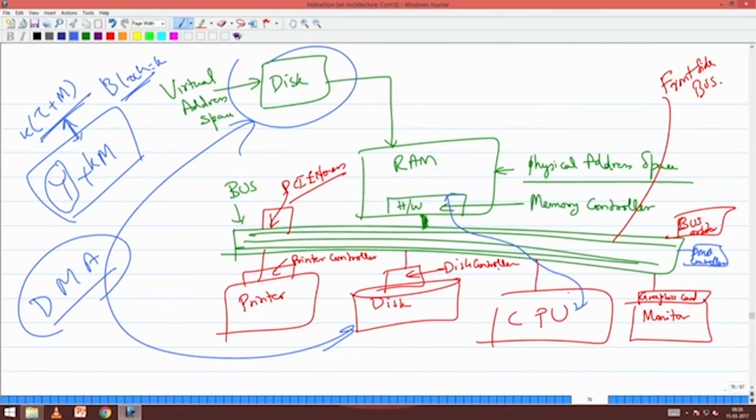What I do is, when I am accessing RAM, I just bring a block of data. I need one byte, but I don't bring just that byte, I bring a block of bytes, and that I need to store somewhere, and that is some storage which is on the chip. So this is why it's called on-chip storage.